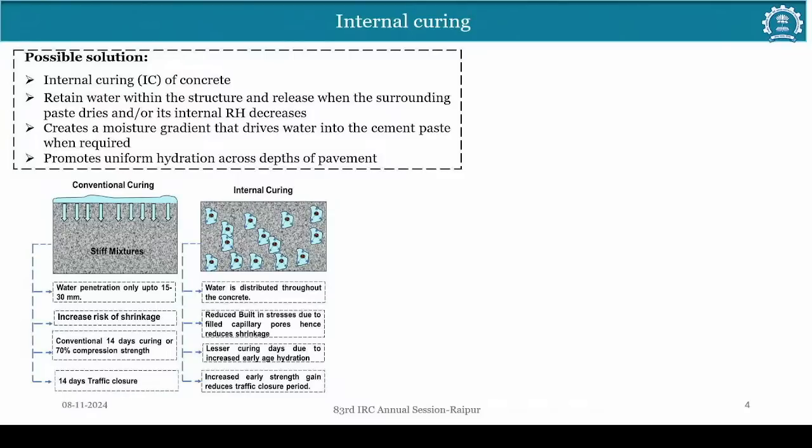So in the internal curing, water is distributed throughout the concrete. As we see in the conventional concrete, we were curing from the top, but here inside it is distributed throughout the structure. And because of this uniform distribution and moisture content present, it will reduce the built up stresses in the concrete, and it will reduce the shrinkage. So this will also require fewer curing days since we are increasing the initial hydration due to the curing.